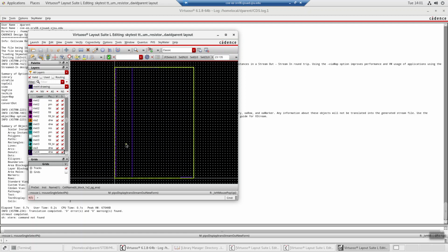If you don't want to deal with the routing so much, you could probably move this over here, right, to get the pins that you need. So for an op amp, the power and ground are already there, so you just need V plus, V minus, and V out. And then if you can squeeze in the multiplier, you just need V in and V out, because we've configured it as a squaring circuit, so you don't really need two inputs.